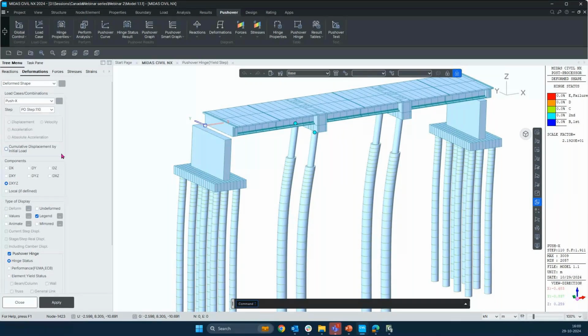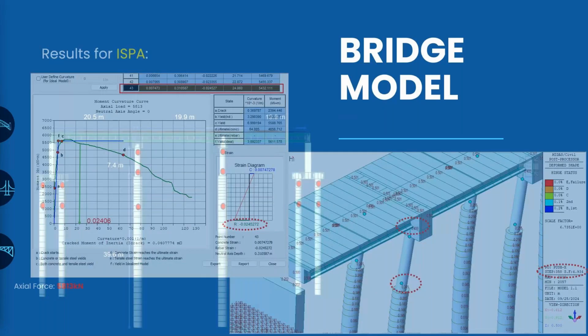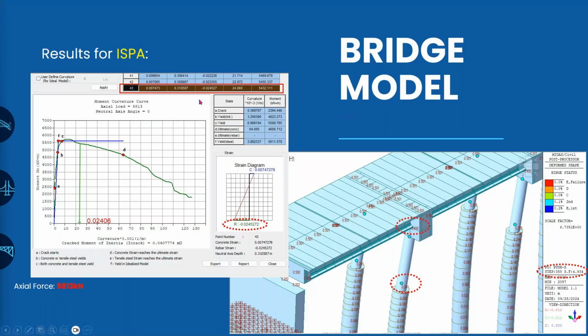Now I have to specify the deformation in this case such that the strain limit is achieved. For this, let me switch back to the PPT. In this case, I have to compute the strain. I'll find the point at which I'm getting a strain of 0.025, which is my limiting strain for the service limited performance case.